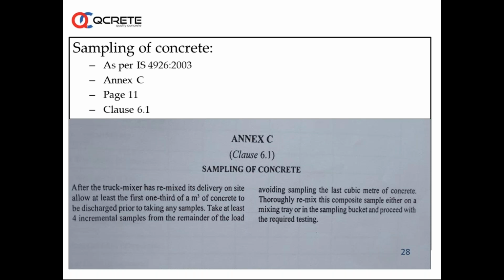So this is very, very essential, as I said, because we are talking about a representative sample. If somebody says, no, I want to take it in the middle, I want to take it at the end, I want to take it this way and that way, that is not a proper procedure and that is not as per standard. The answer is very simple: we cannot do it like that because this is not defined. Most importantly, we comply with everything when we talk about steel, and we comply with everything when we talk about other metals. But when it comes to the standards of ready-mix concrete, whether it is sampling or testing, we try to be more creative and probably define our own methods.